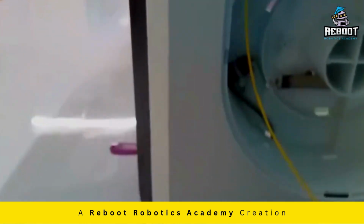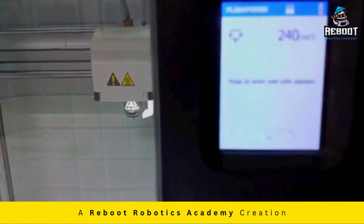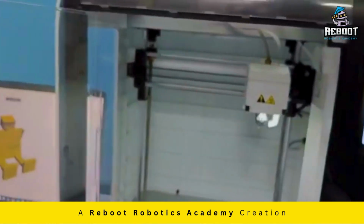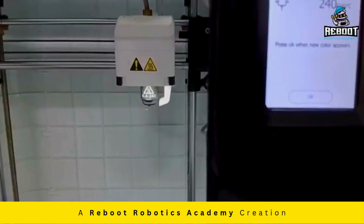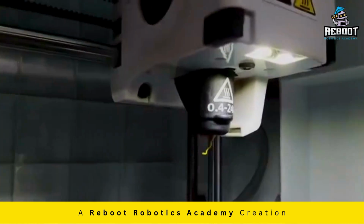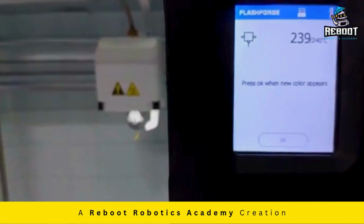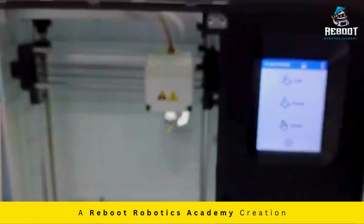So now the filament is getting taken, as you can see, and it is saying that we need to press OK when the new color comes. So we will be opening the 3D printer glass now. We would wait for the extruder to emit yellow filament. Now I would like to show you that the yellow filament is coming. The next thing we will do is press OK. Now our filament is set.